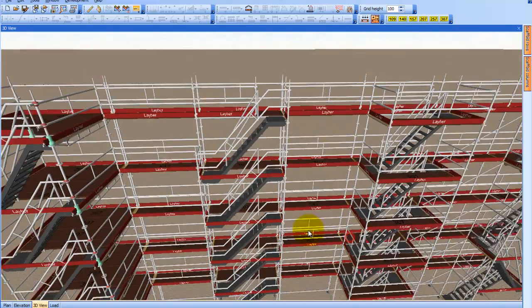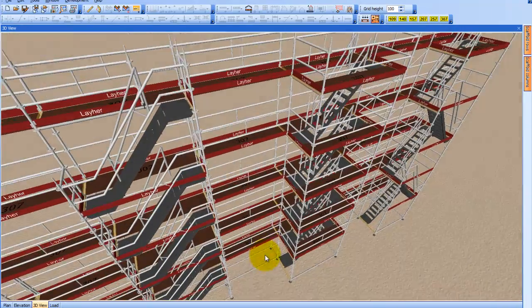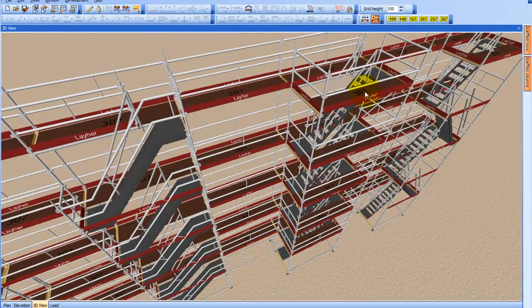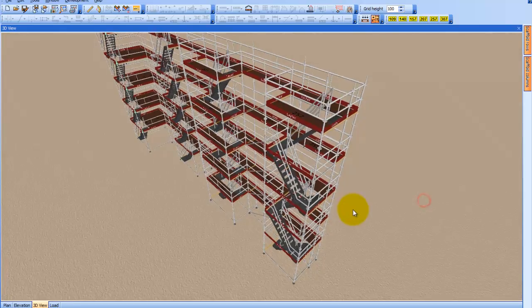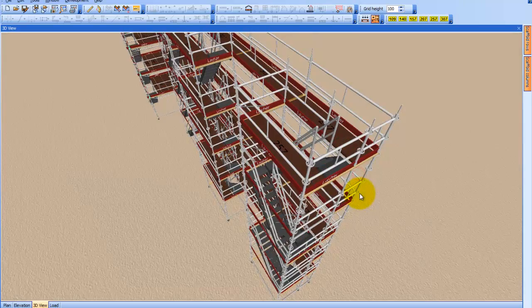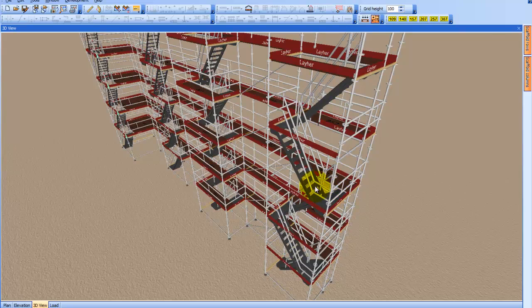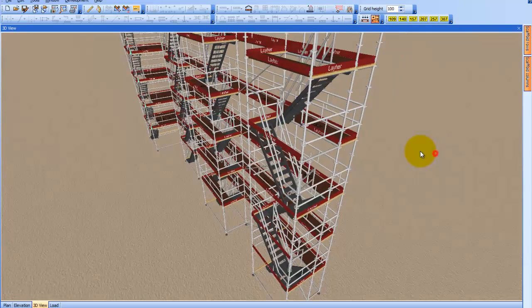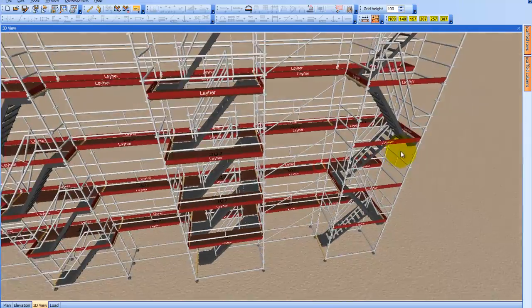And we have a double, with the same alignment, which means that you have a deck level that you can walk around without actually interfering with the scaffold. And finally, we have a double stairway, which is a complete unit, where you actually turn around on the stairs and go up. In this case, we also have inside guardrails and other protection features installed.